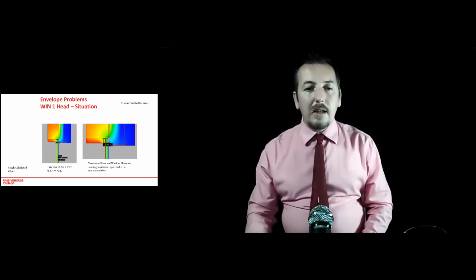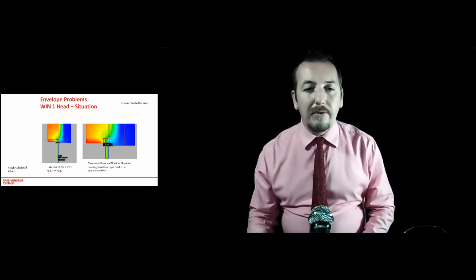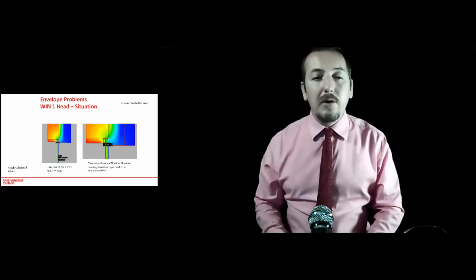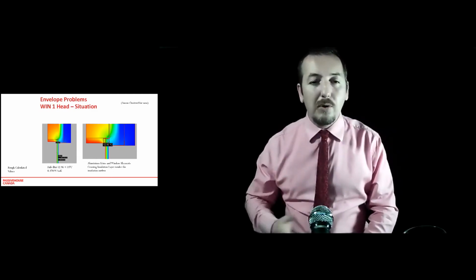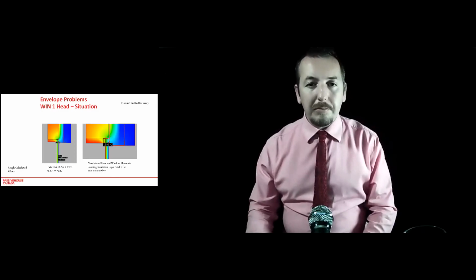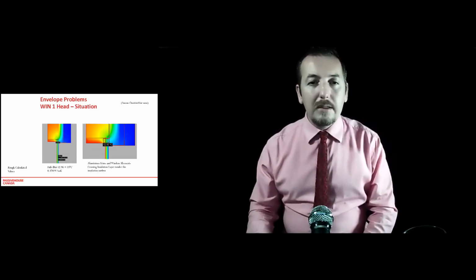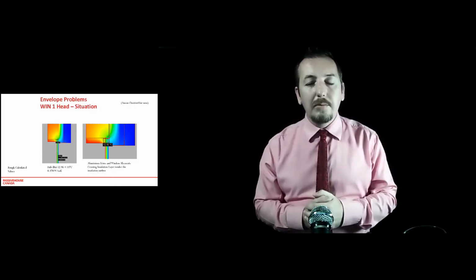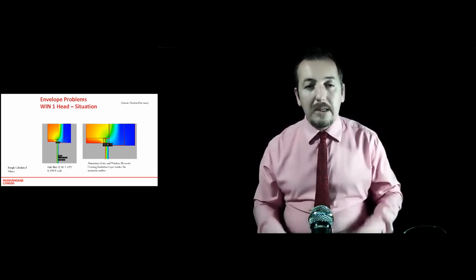So this detail came out at 0.374. Generally, for a passive house window fitting detail, you could be as low as 0 or 0.01 or 0.04. And the reason that this detail actually ended up so bad, even though we'd spent all this on insulation and labor, was because when you try and overlap an aluminium frame, it's basically pointless.